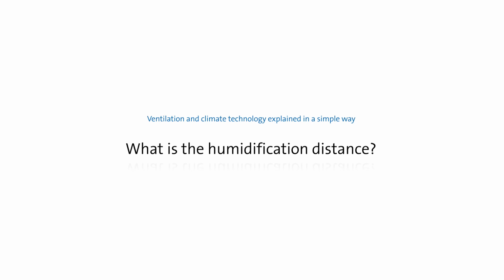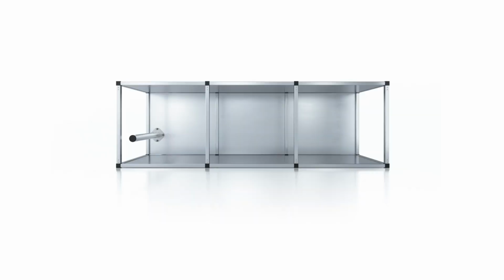Humidification distance. What does it mean? Any steam leaving the steam distribution pipe needs to pass a certain distance until it has been fully absorbed by the air passing through, until it is no longer visible as mist. This distance is called the humidification distance Bn and serves as the basis for the calculation of the minimum distances to the components installed downstream.